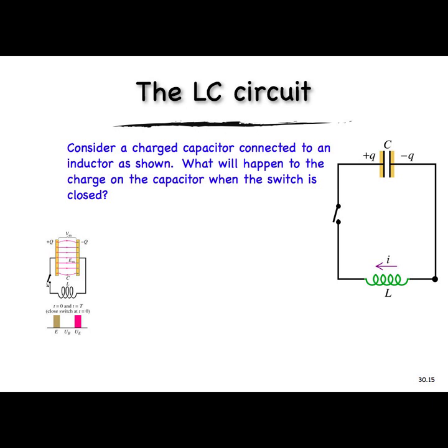So what I'd love to show you, I'll keep hoping. This is a little harder to see. That peak is 400 volts. So I'm getting 400 volts. That's why I had to divide this by 10, right? If I had not done that, I'd damage the oscilloscope. That 400 volts is much larger than the 2 volts that I'm driving the circuit with.